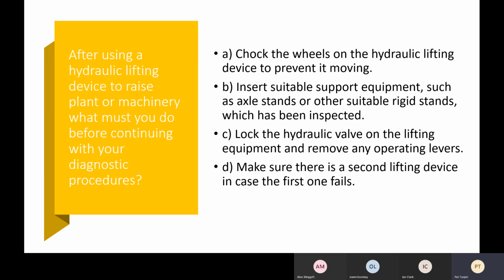So, you know, it's all right lifting something up. You've got to make sure it doesn't move. Even now I've lifted gearboxes up onto benches, and as you slide them forward, it pushes the lifting device backwards, so you risk it tipping off the bench. Little things like that. You've got to make sure that they can't fall. So in that instance, yeah, axle stands or suitable rigid stands, something that's been inspected as well. Don't just wedge a bit of pipe under it or a bit of plate. You know, it needs to be a proper job that has been inspected and stamped to say, yeah, it's capable of doing this.